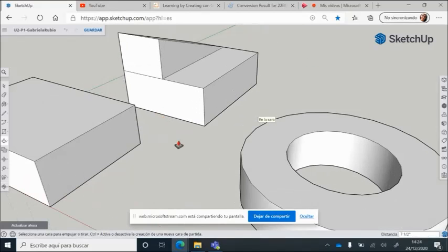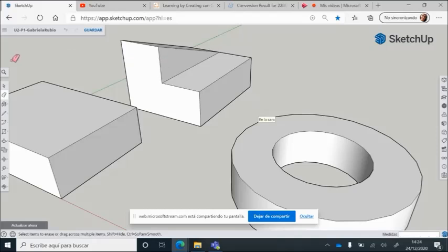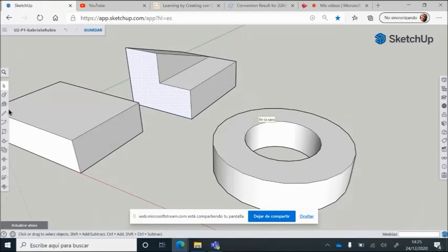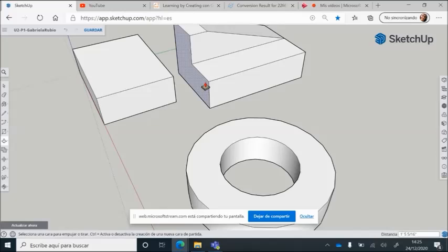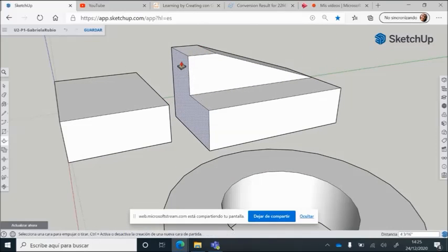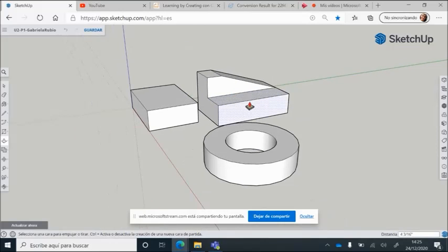Right before passing to that point, I want you to understand how this surface, because it's part of the same plane, we can make it an only surface because it is now divided into this square and this rectangle by selecting this edge and deleting it, right? So we click on the eraser and we delete it. So now we only have one surface. We could work on that surface as an entity. So we can, for example, extrude it again, and you see we will create a horizontal part here because of course this surface cannot grow in height, so this would be our object.